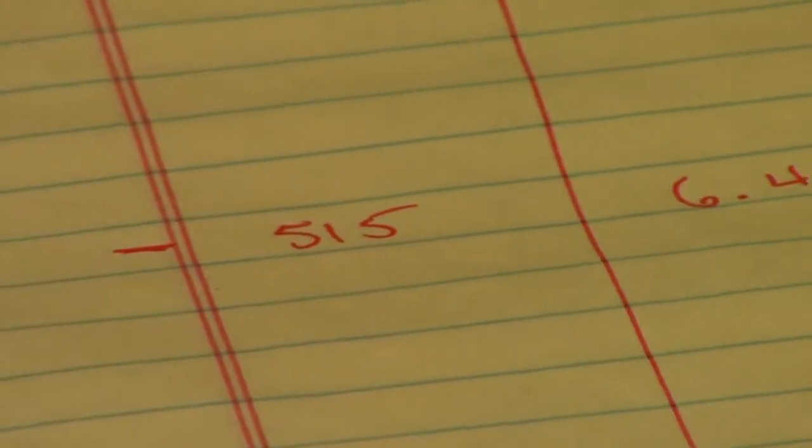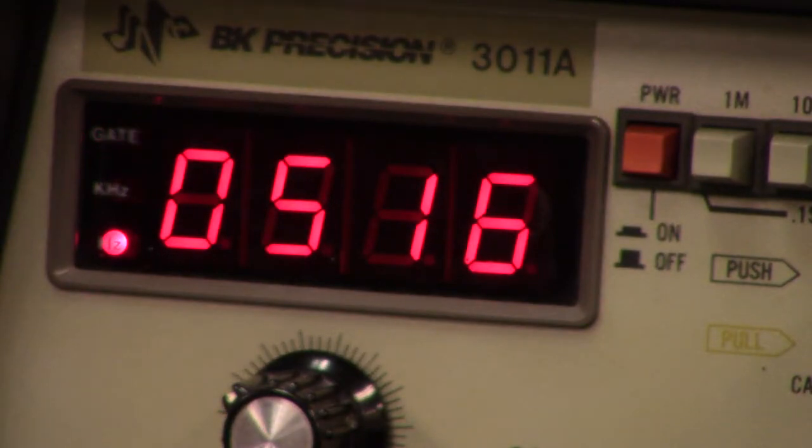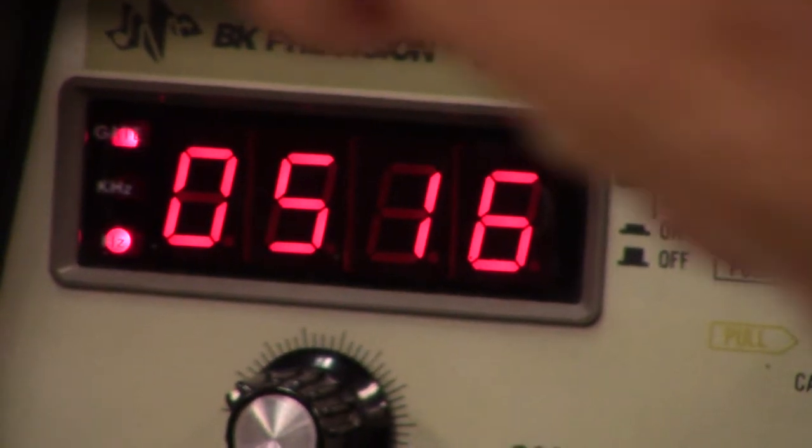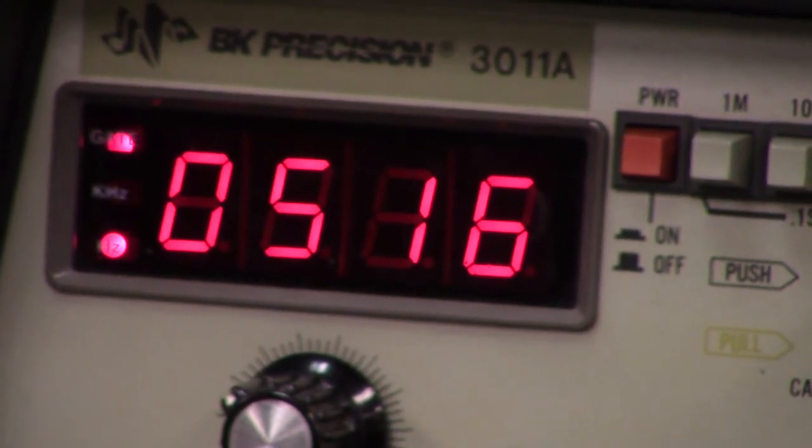Now that doesn't mean more current, by the way, because remember I'm dividing by 100, so it'd be 0.06. That's actually less than over here of 0.2. But the number on the voltage makes it almost look like we're getting something bigger with more resistance, and we're not. More voltage, perhaps, but not as much current. And that's what we're focusing on, the current we're getting. So more resistance should be less current, and sure enough, that'll come out that way once I divide by 100, because that'll be 0.0644, whereas this one, when I divided by 10, was 0.272.